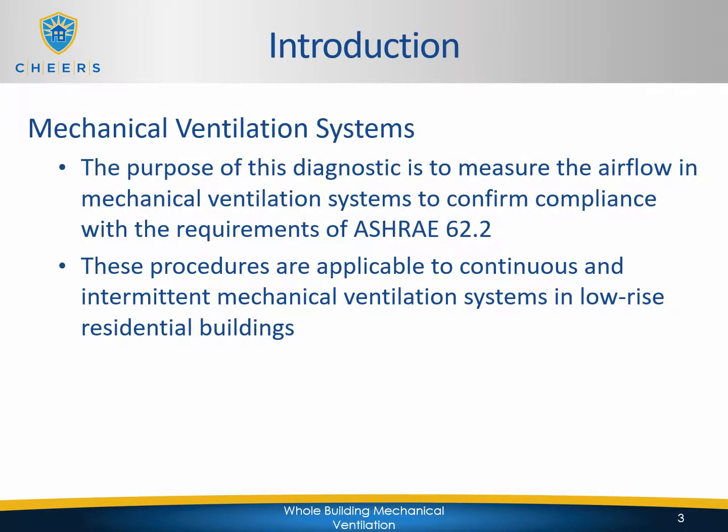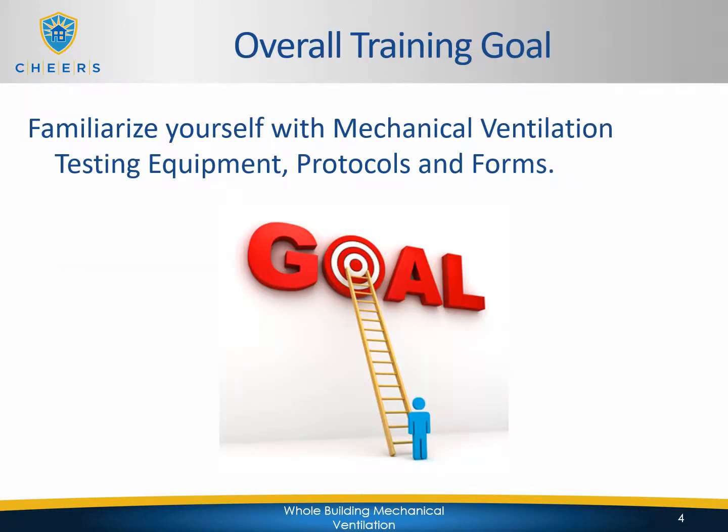The purpose of this diagnostic is to measure the airflow in mechanical ventilation systems to confirm compliance with the requirements of ASHRAE 62.2. These procedures are applicable to continuous and intermittent mechanical ventilation systems in low-rise residential buildings as previously described. The overall training goal is to familiarize yourself with mechanical ventilation testing equipment, protocols, and forms.